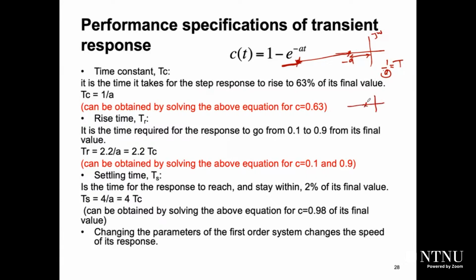Okay, you have a system pole here, correct? And you have a system pole here. So what will be the response? Choose the response, right? The response here will be something like this one, or something like this one. Here the time constant is larger. The time constant here is smaller, right? Just remember that this one is A. Time constant will be 1 divided by A, right? When A is large, the time constant will be smaller. So in fact, this one is the response of this one.